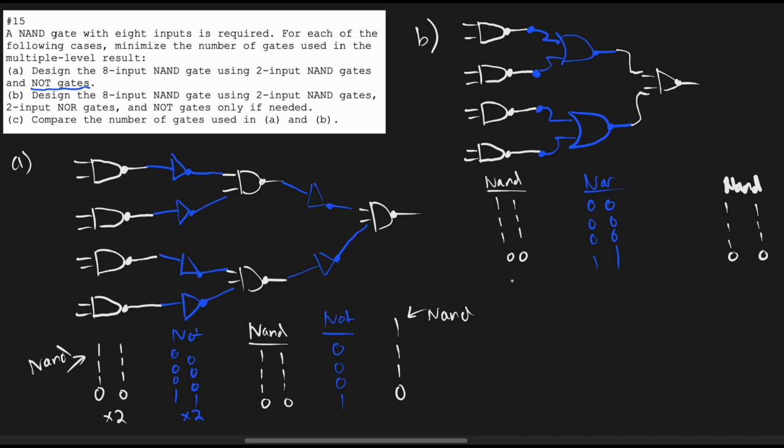Keep in mind for the NAND, we have 2. And so if we take the NAND of this, and I'm going to erase this so we can redo it properly, we are going to have NAND, and the NAND of 2 0 inputs is 1. We're going to have 1, 1, and then 0. And so we've done it. We've gone to a NAND gate at the end using the 8 input NAND, 2 input NAND for the end, and then the 2 input NOR.